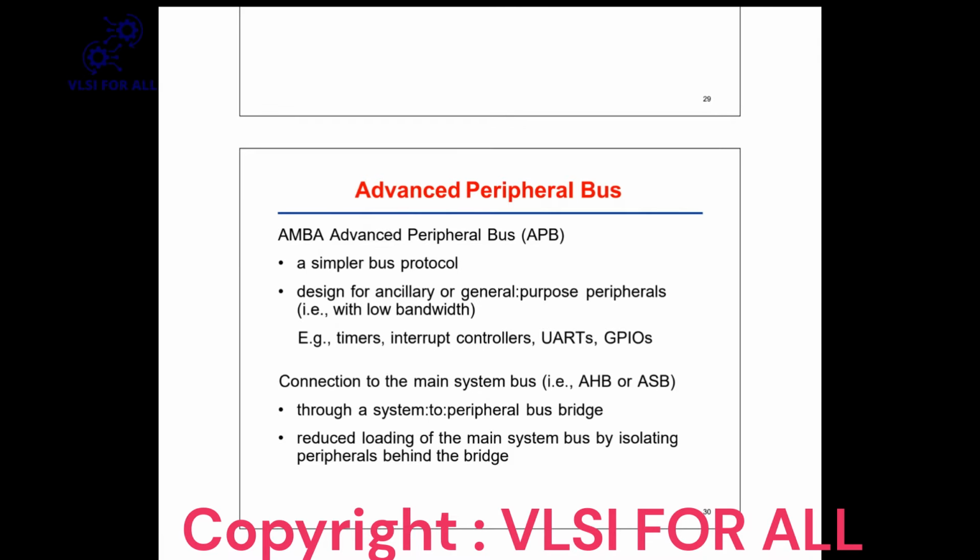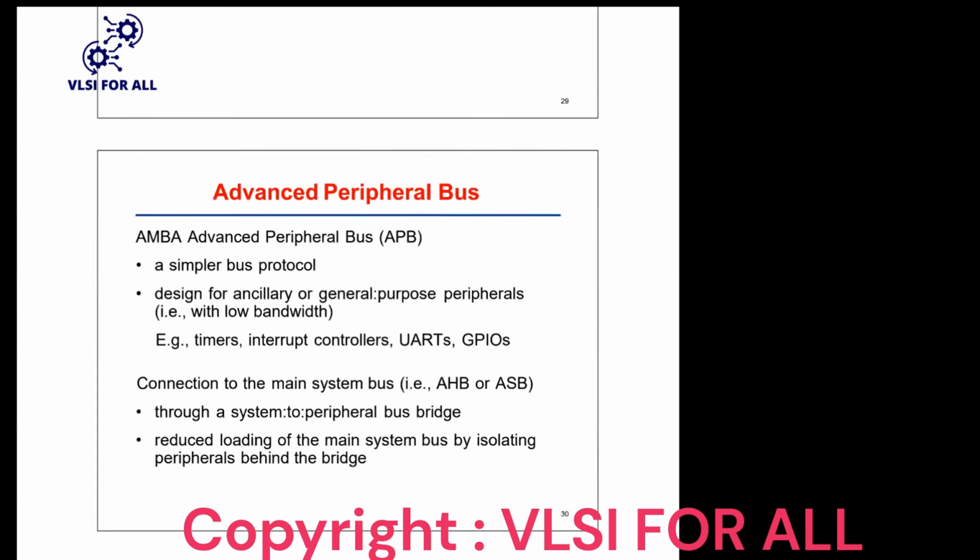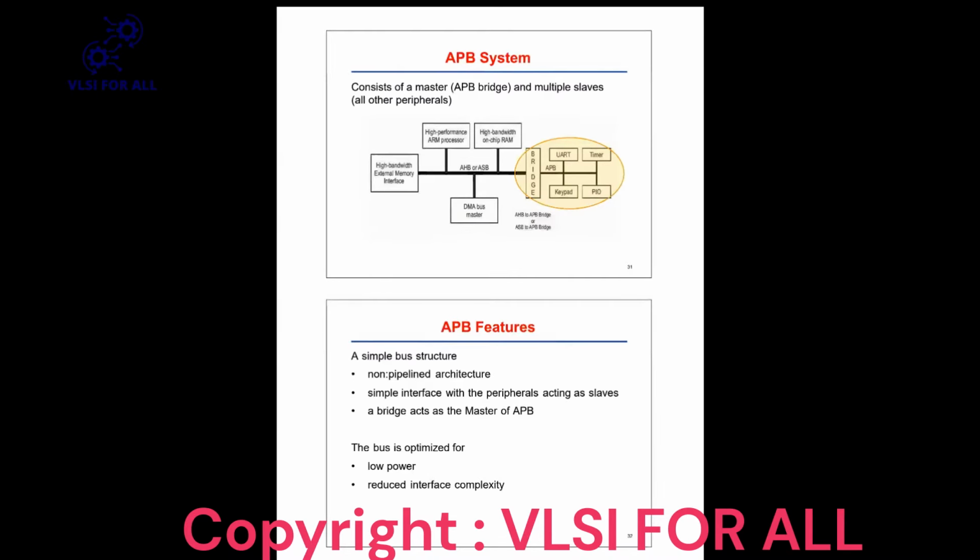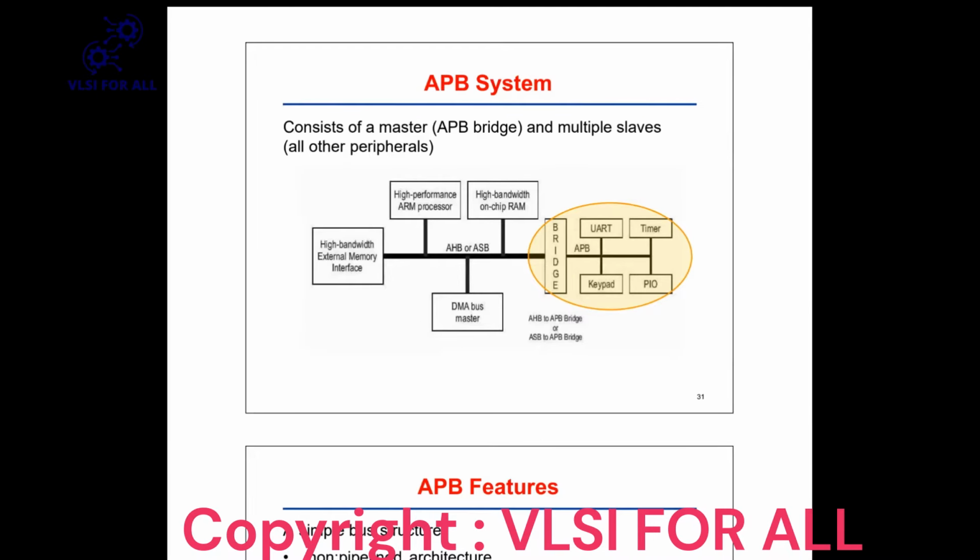Also you have to say why two clock cycles, and that will get cleared through the state diagram. In APB we have a state diagram with the idle phase, setup phase, and access phase. When that setup phase and access phase come, there is the answer. In a further slide we will see why two clock cycles are required. Is it clear, guys? Okay. Yes, sir.